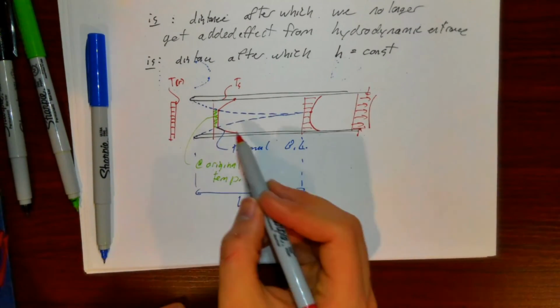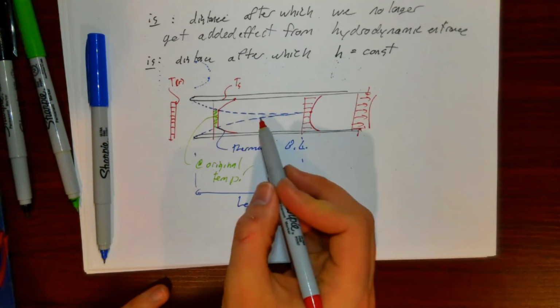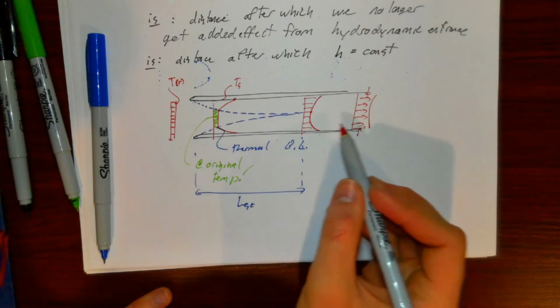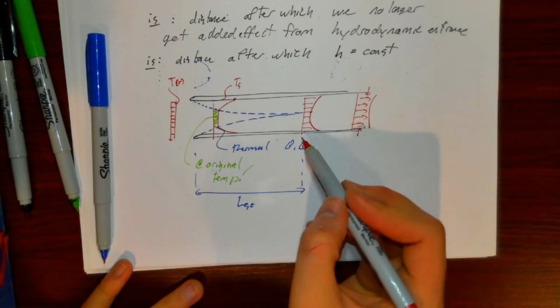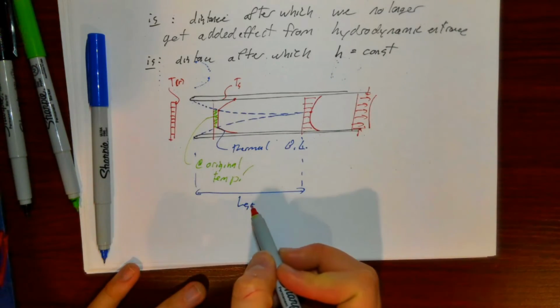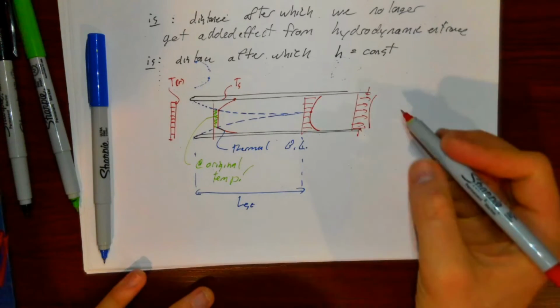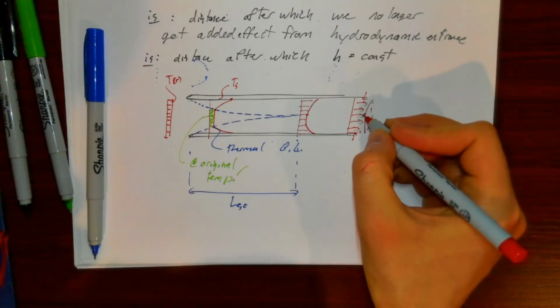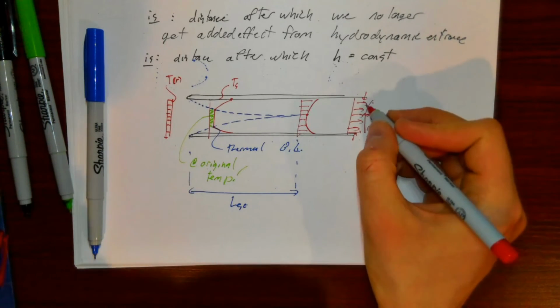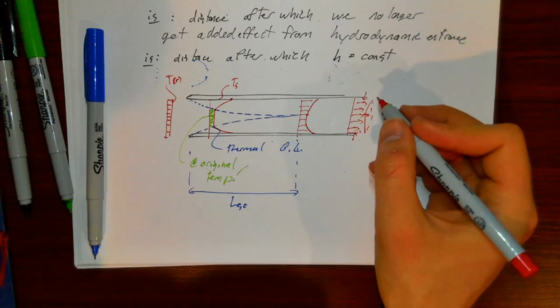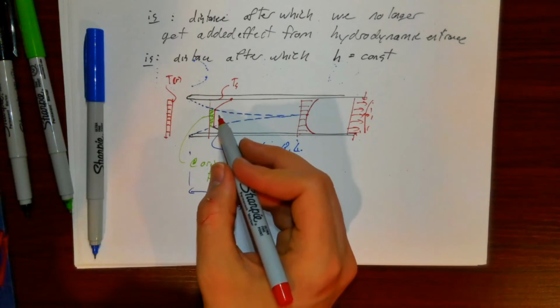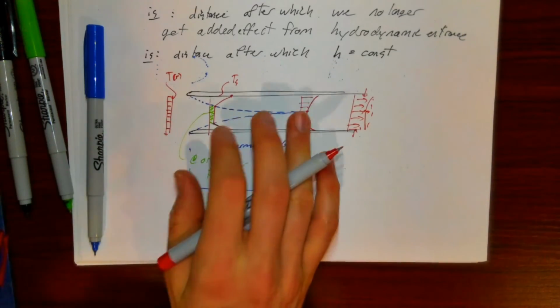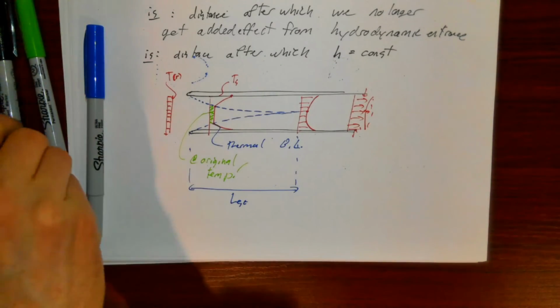So here you have these thermal boundary layers that are growing in from the edge. It's not that all of the fluid has entirely reached the surface temperature by the time you're past the thermal entrance length. It's just that some point in the fluid has. And your fluid core temperature still might have a ways to go to get up to the surface temperature. It's just at a point where it's now not completely unaffected by it.